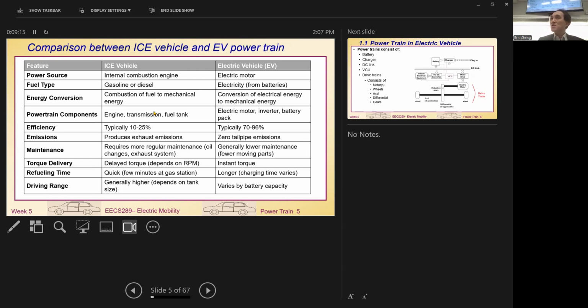Why is that? Because for braking, we use electronic brake. We still have the mechanical brake there, but we seldom use it. If you drive the vehicle, you know that you always press the gas pedal. You don't really need to press the brake. So the brake pad is there, but you seldom use it, which means it doesn't get any wear and tear. And there's little lubrication oil. No lubrication, no hydraulic system. Only the motor, and the motor uses bearings. So you don't need to worry too much about lubrication maintenance.